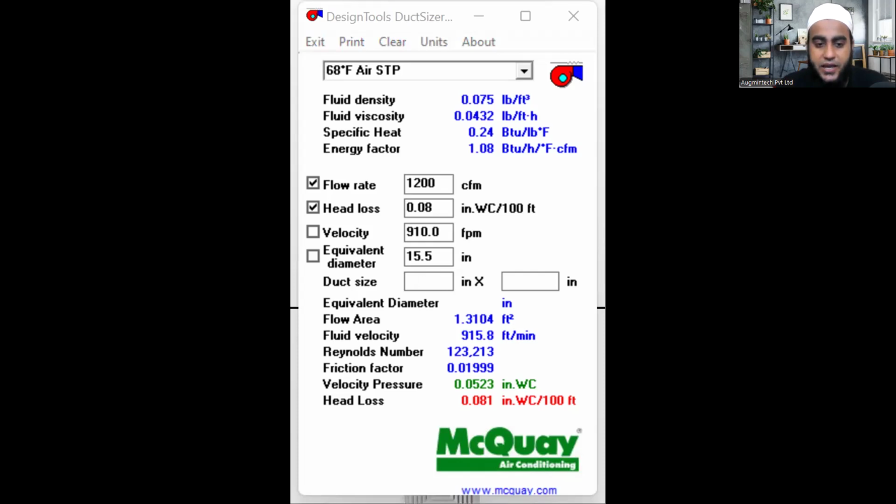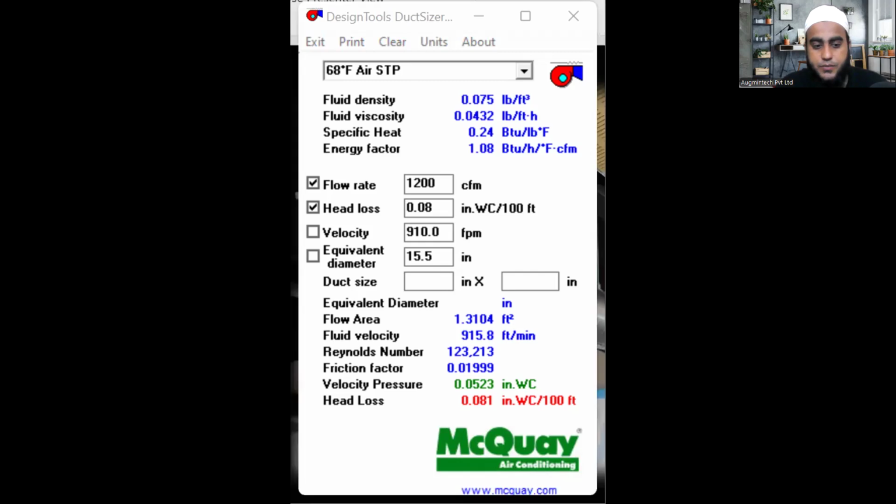So let's say in my case, what I am doing, I'm assuming, suppose this is one room. All of you just listen carefully, okay? I'm drawing the section of that room. Suppose this is my room, a cafeteria, for example. And here we have a false ceiling like this. This is the FFL, finished floor level, false ceiling level, and slab. So suppose the height available here to run the ductwork is around 400 mm. Height is given by the architect side.